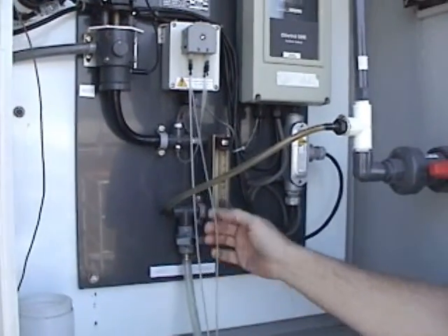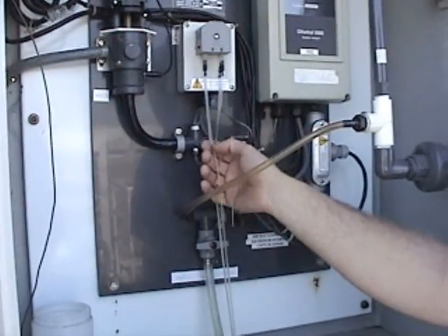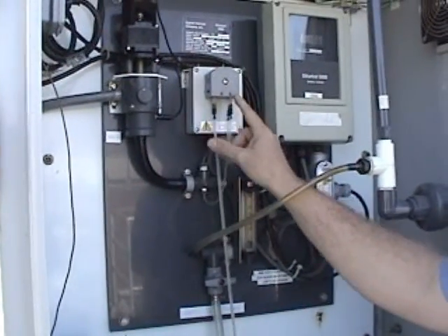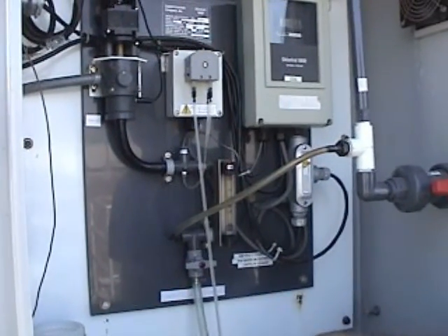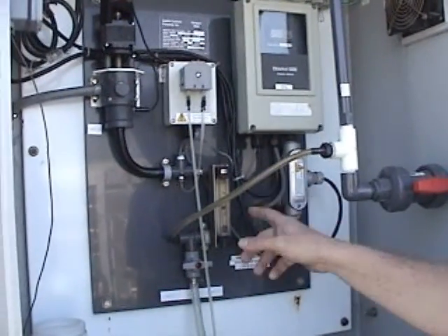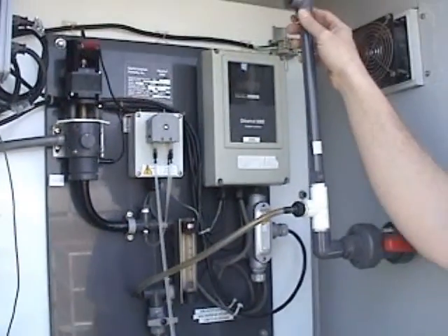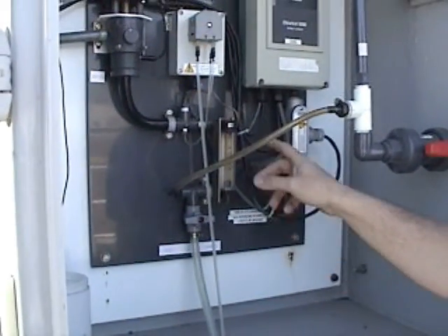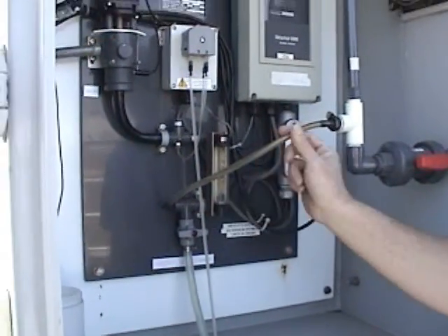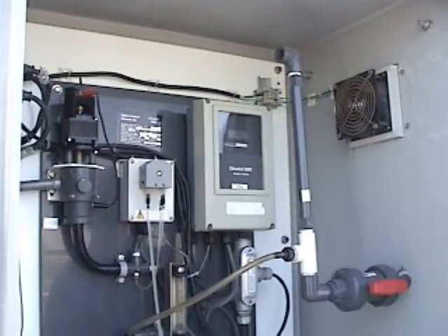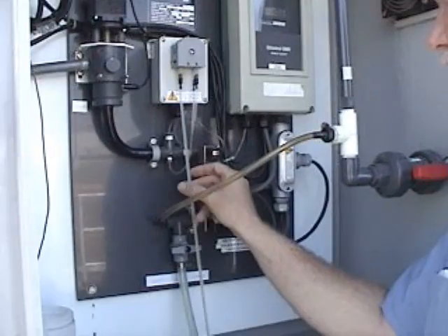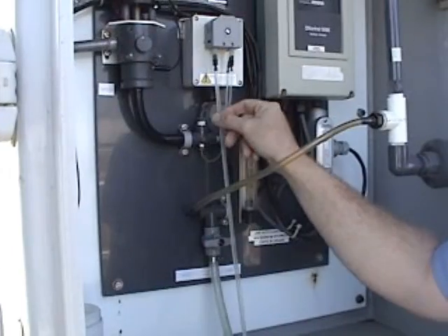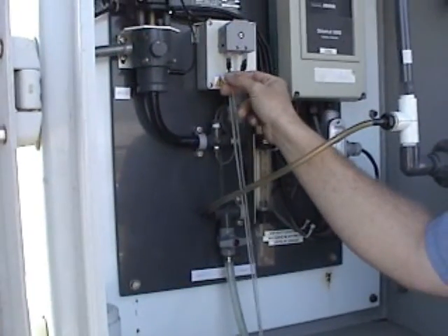How would you see it? You'll just see little tiny air bubbles in here. You can squeeze the tube like that and help the air bubble pass through that peristaltic pump. To help with it, you have this little chimney right here, this little standpipe. The idea behind that was to release the air. You're pulling your sample out, and hopefully the air will pass through here and go out of this pipe. But that's what you would do. You'd see little air bubbles here, and you try to help them out by pinching this tube. And that's something you could do at night.